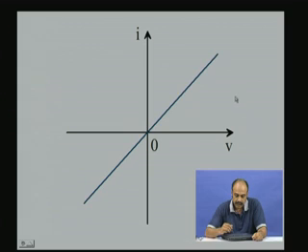So, in this IV characteristic, we plot the character of the resistor, as you see here, is a straight line, and the slope in this case is I by V, which is 1 by R or 1 by the resistance value. So, this is how the resistance is described.